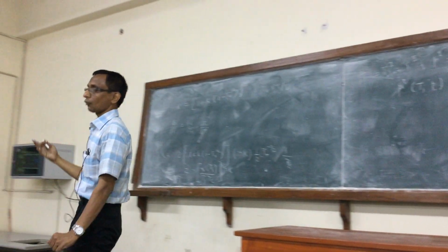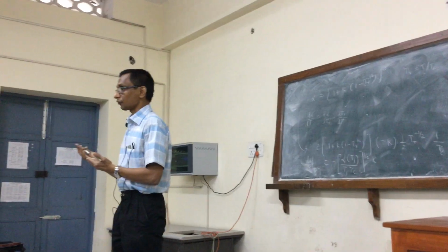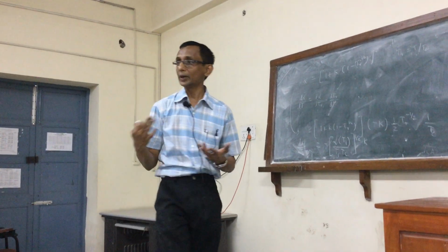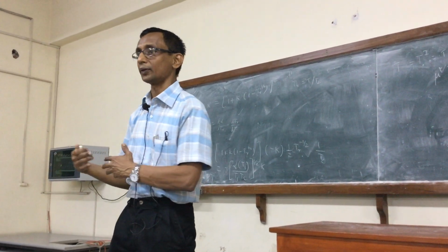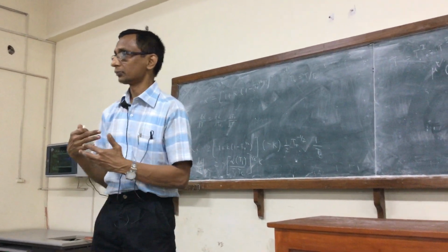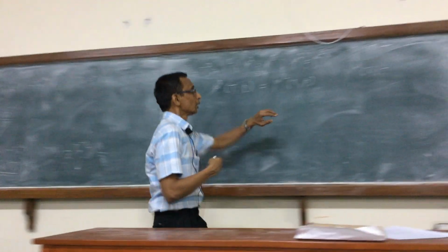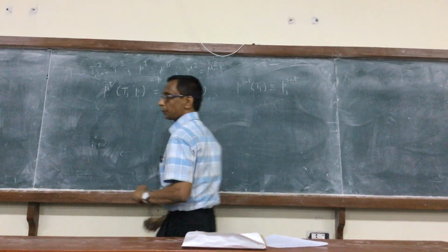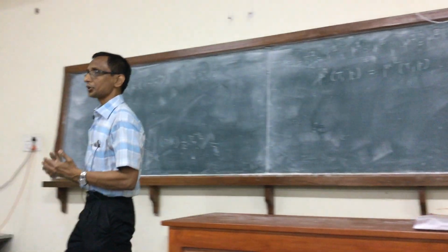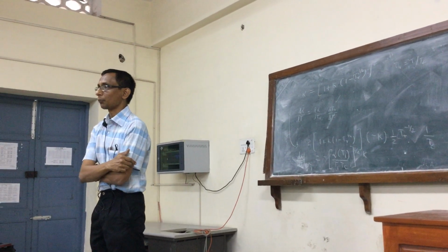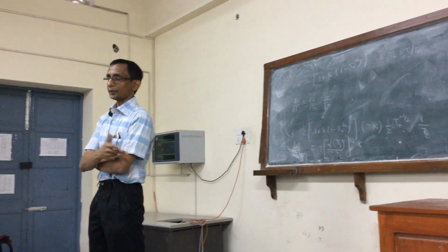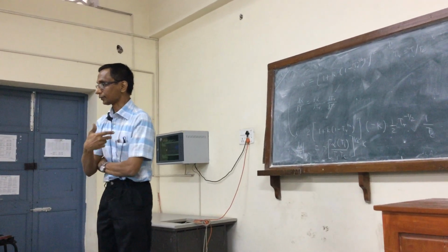That means one equation, one variable can be solved in terms of the other. So there's one degree of freedom only. Temperature and pressure both are not independent variables. So this is constrained on the temperature and pressure. Right? So let's say I call this P1 sat. So I want the saturation pressure at a particular temperature T1 that's given to me, right? I'll call that the P1 sat, that is the saturation pressure corresponding to temperature T1.